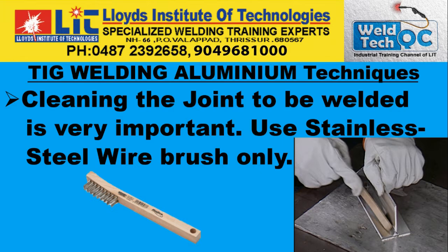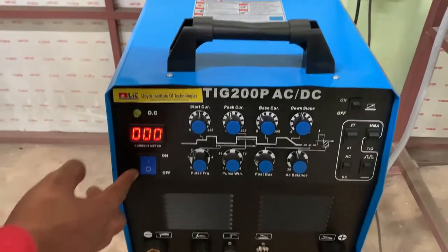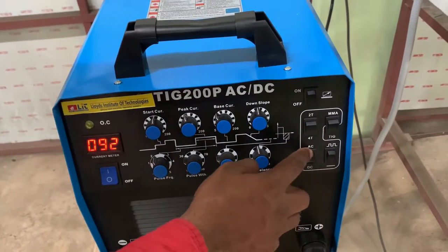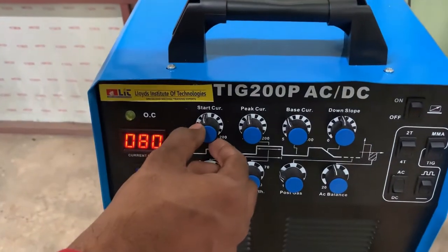Better to use a stainless steel wire brush, and most of the oxide layer can be removed by that, and the remaining will be taken care of by the alternating current. Alternating current is the most preferred current to weld aluminum, as just said.